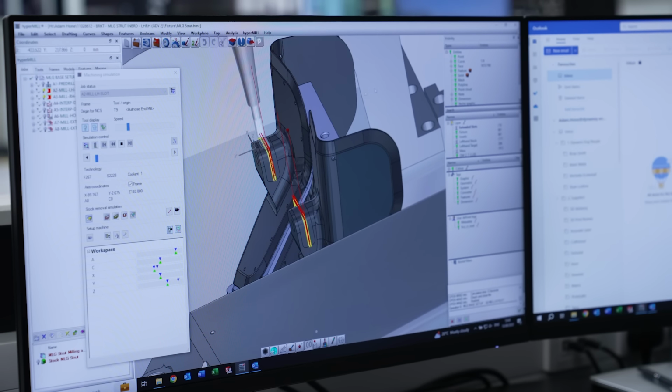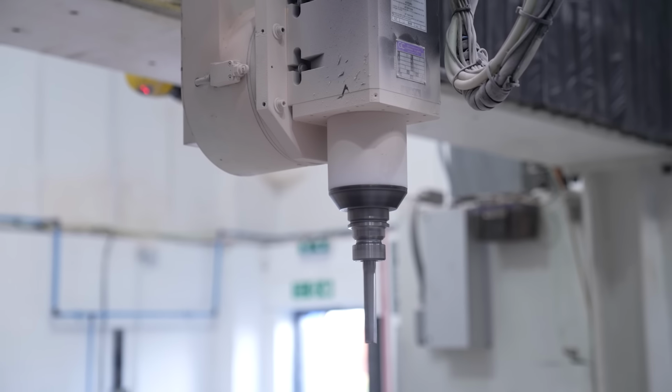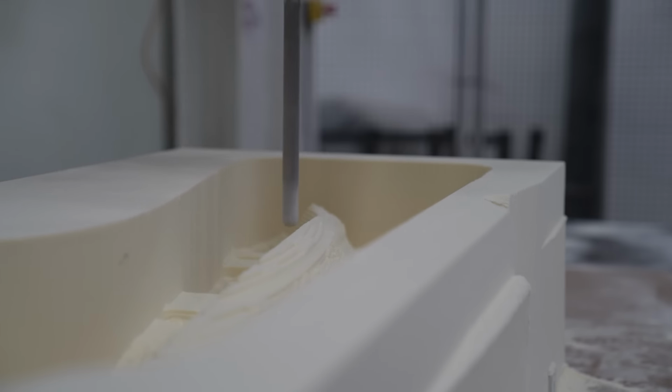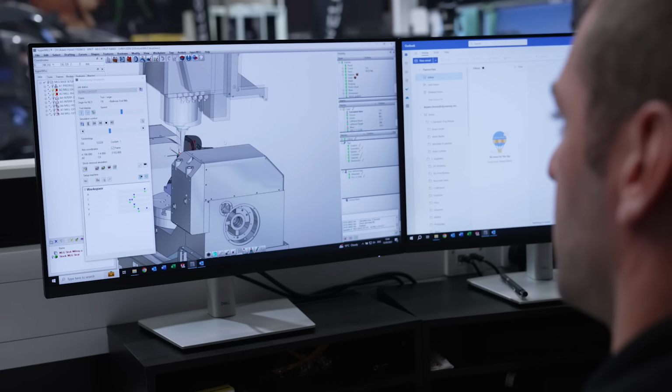So Virtual Machine and Optimizer on the gantry mill is ensuring that they cover things like rewinds automatically. It means as a programmer, you program as normal, even though the machine is complex. And with having the digital twin setup and Optimizer, we automatically ensure that it is collision free and it can run within the machining envelope comfortably.